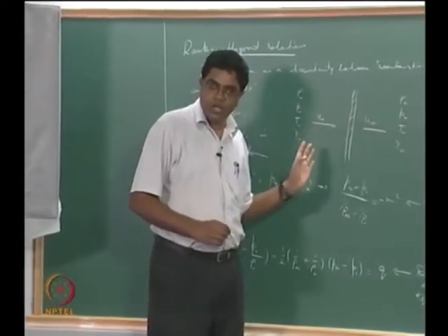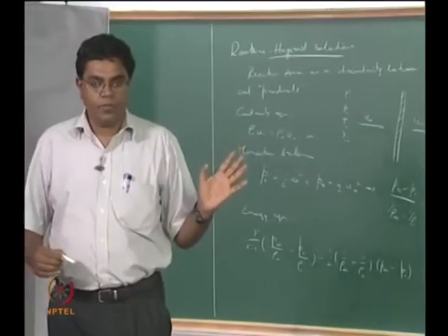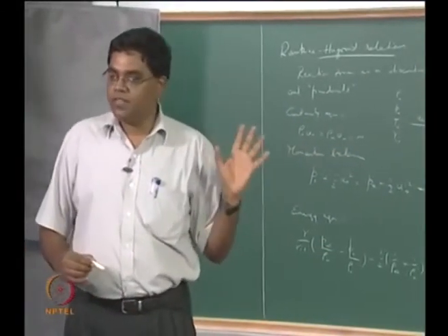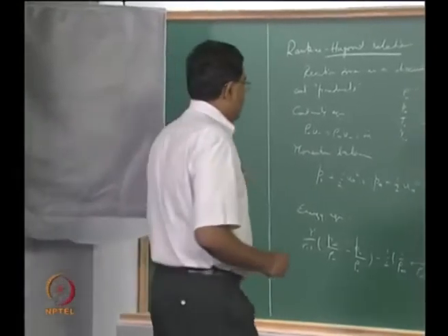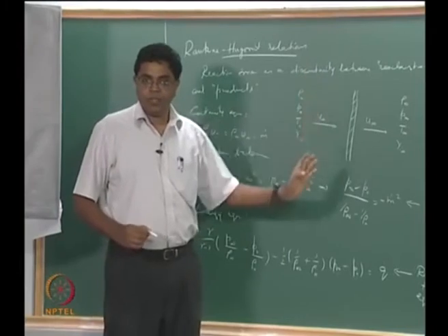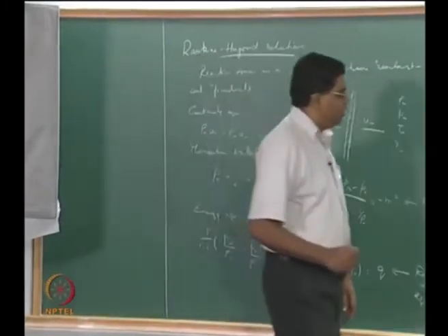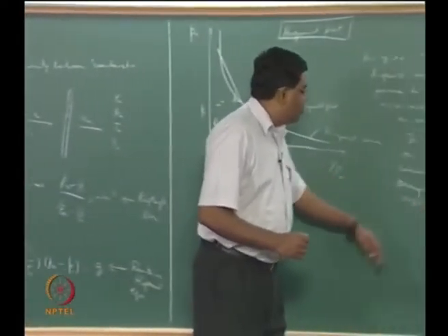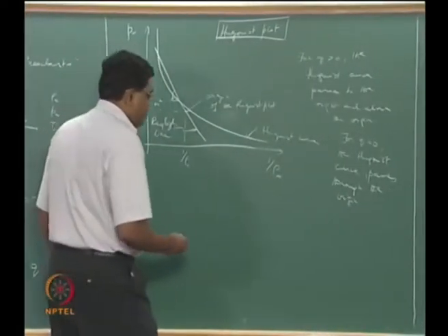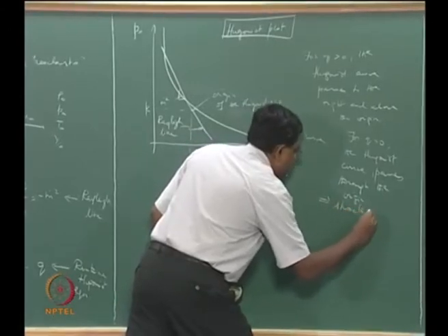So across a shock you would find that the stagnation temperature, particularly the stagnation enthalpy, remains the same. That is true when you do not have any chemical heat release. So a curve that passes through the origin with Q equal to 0 is what is called the Shock Hugoniot.